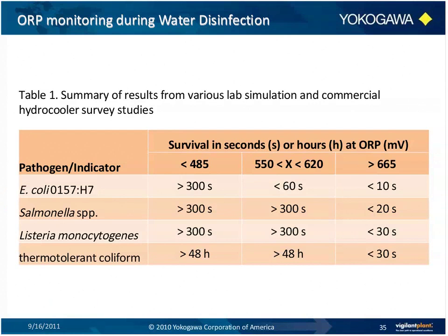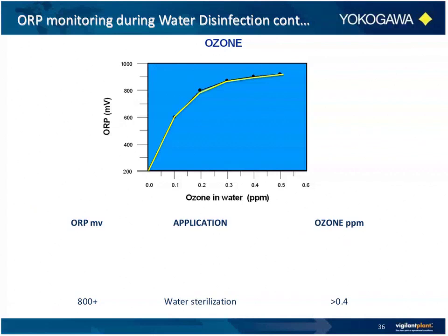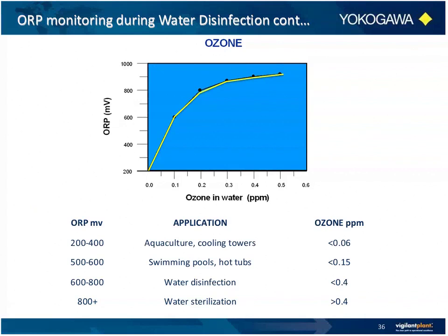However, a disadvantage to this method is that a combination of ORP and ozone concentration monitoring is necessary to ensure proper water disinfection. This is because the resistant spore-forming decay pathogens and human parasites present in the water are highly tolerant to chemicals such as chlorine, bromine, and iodine, and other weak oxidizers commonly used for water disinfection. However, in clean, potable water, ozone has been proven to be a highly effective sanitizer at concentrations of about 0.5 to 2 ppm.